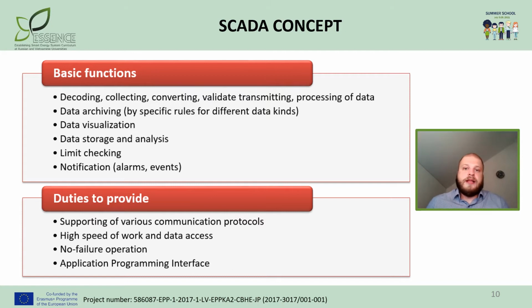And the last, but maybe not the least important, point is data presentation. A real SCADA system reports to human operators over a specialized computer that is variously called a master station, a human-machine interface, or a human-computer interface. The SCADA master station has several different functions. The master continuously monitors all sensors and alerts the operator when there is an alarm, that is, when a control factor is operating outside what was defined for a normal operation state.